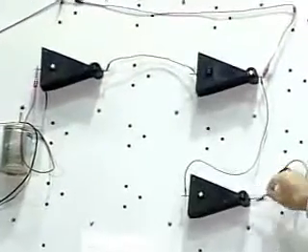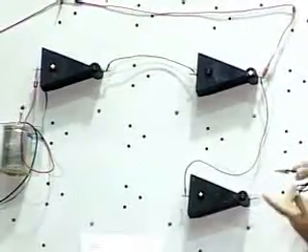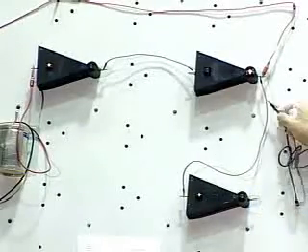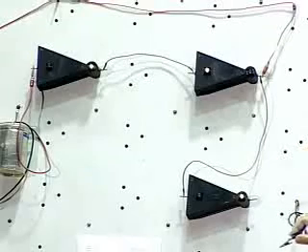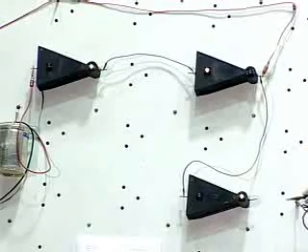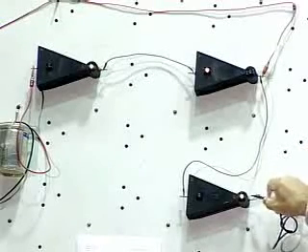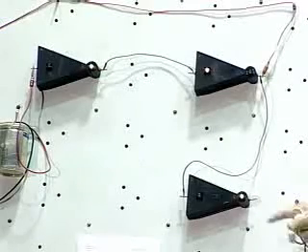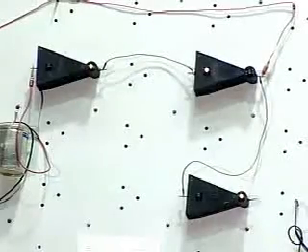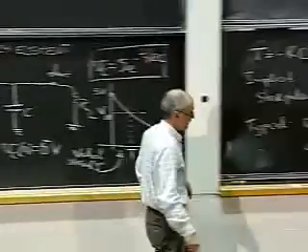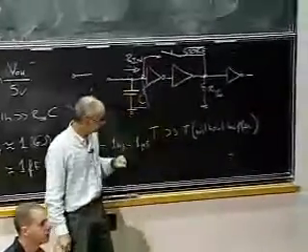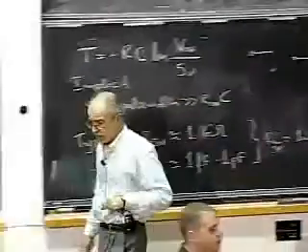Now of course I can do anything I want here. Nothing happens, but you may say this is a trivial case because this is already 0. So I'm going to change the state. Here's the state changed. Now, see, I can short this. Nothing happens up there. So this is an interesting situation in which I'm buffering the output so that the output does not feed back to the input. And by and large, in designing circuits, this is something that we do.